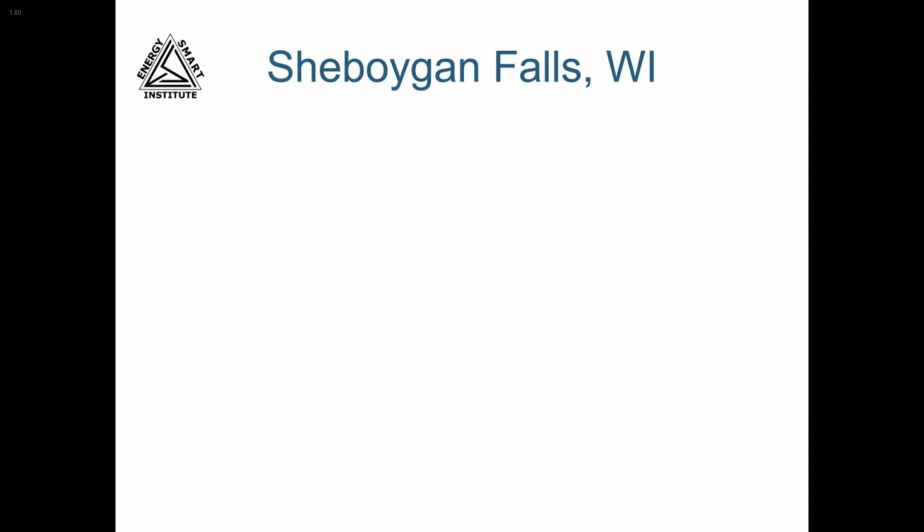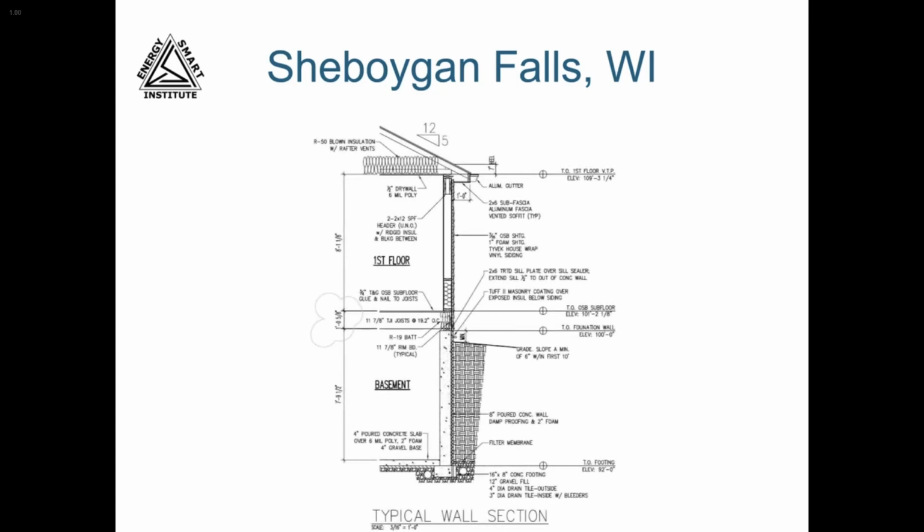Many times, the floor plans will show ceiling heights under the room names. This plan doesn't do that, so we can look at a section view to determine our ceiling heights. When we look at the section, we see that the basement is 7 feet 9.5 inches tall, the joist area is 1 foot and 5/8 inches tall, and the first floor is 8 foot 1 1/8 inches tall to the drywall